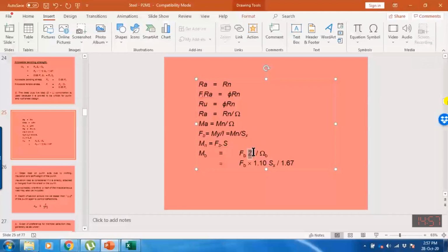ZX is a partial section modulus or complete section modulus. That is difficult to explain at the moment, because we will study it in our beam design chapter. But here, we use this equation, and instead of S we use ZX, because our section will be plastic: it will locally yield and it will not buckle.